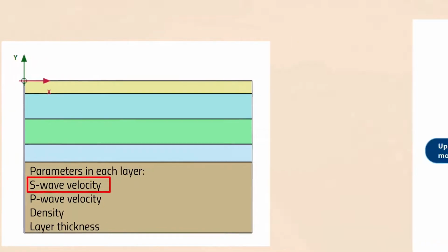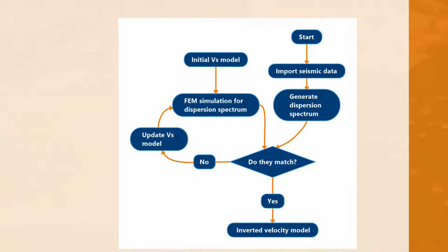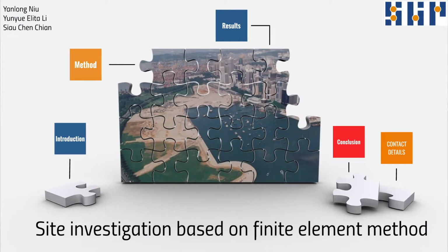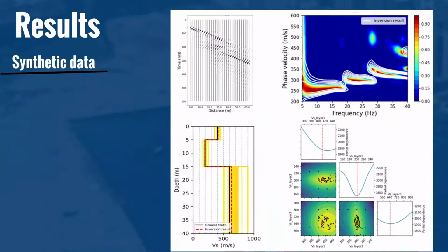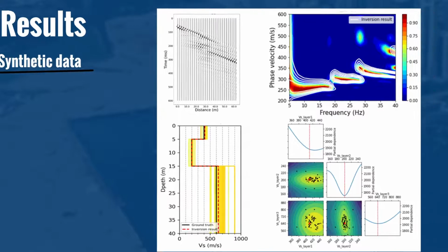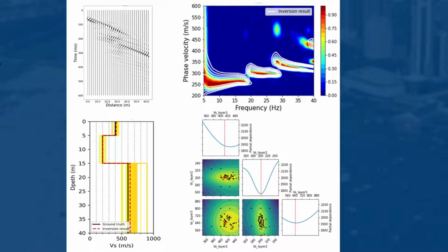in the inversion procedure. Now we have discussed all of the critical elements in inversion, including the persistent distance, objective function, and Bayesian optimization. So how is the performance of our new framework? We test our framework on synthetic data. We simulate a particular three-layer soil structure that contains a low-velocity layer. Such a soil profile generates a complex shot gather due to the soft layer, as shown in the upper left.